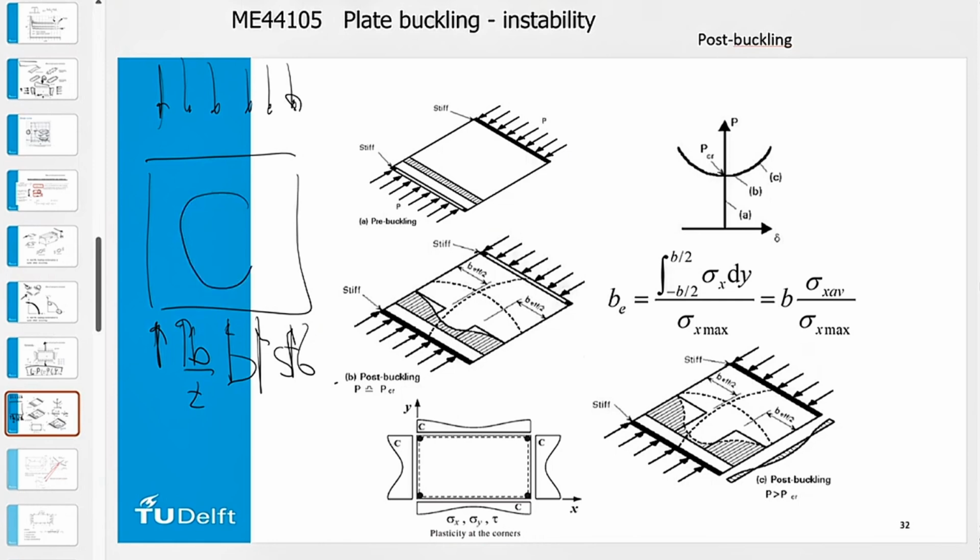And then I might have initial buckling, but the edges of the plate have still some stability because they are connected to the side plate. So I can also take into account, okay, if I take at the edges the yield limit up till this 13 or 14 width, because if I have a plate buckling which buckles much lower, the linear plate buckling is a lot lower than the yielding of the full plate, then the edges still can go up to the yield limit before they buckle. So there is some kind of a correction factor for this.